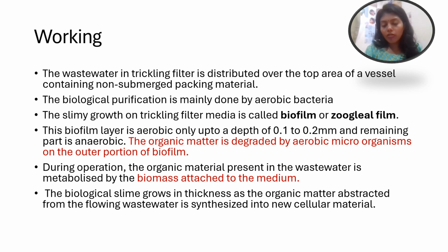This biological purification is mainly done by aerobic bacteria, and the biofilm that is formed is aerobic only up to a depth of 0.1 to 0.2 millimeter, and the remaining portion is completely anaerobic. The organic matter is degraded by aerobic microorganisms on the outer portion of the biofilm. By consuming organic matter, they will reduce the BOD level in the water.